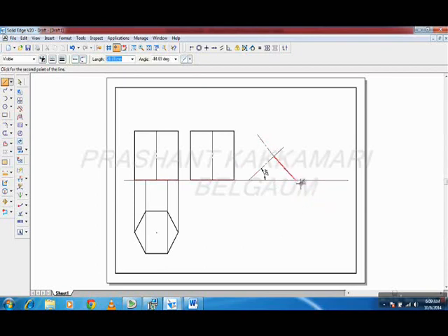Or parallel to this line. Okay, no problem. So what you can do is, I will just extend this line up to here, or else you can go to IntelliSketch. Again you can take the different relationship handlings. So by that you can draw this triangle now. So observe this. Now I will consider this is the base of the prism. This is the axis of the prism which is going up to the tip. Now what is the angle with the axis, 40 degrees.